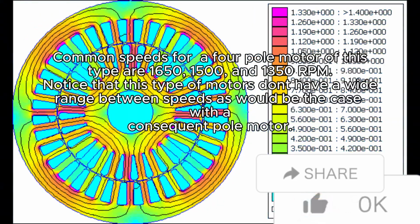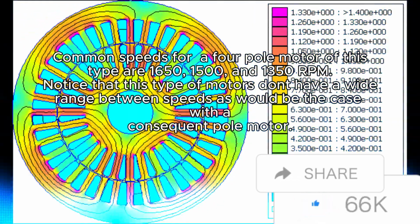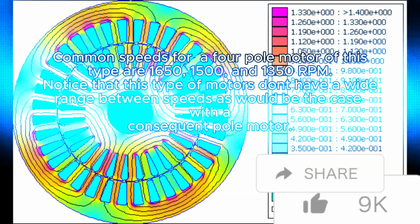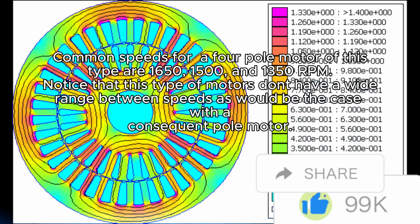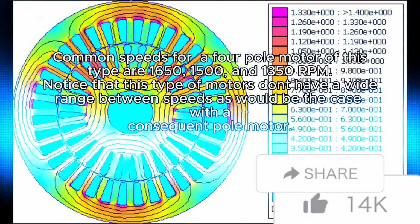Common speeds for a 4-pole motor of this type are 1650, 1500, and 1350 rpm. Notice that this type of motor doesn't have a wide range between speeds, as would be the case with a consequent pole motor.